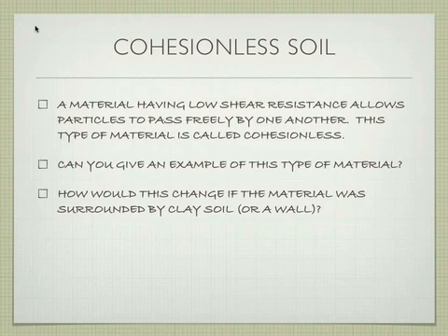Okay, so you've been out at the beach, right? You go to put your foot somewhere, and it slides a little bit. That sliding is this low shear resistance. If you ever try to build a sandcastle, without water, obviously, it's always going to taper out to the sides. It's not going to stay this nice towery shape. That's because it has this low shear resistance, which classifies it as cohesionless soil. Cohesive sticks together, cohesionless dissipates.